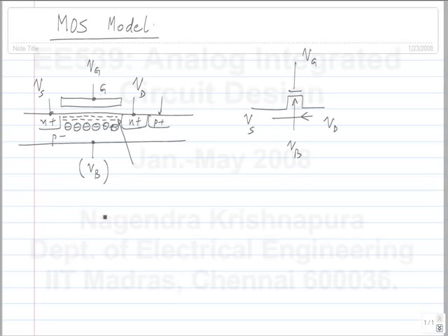So, you can think of this as, think of the MOS, that is how it was initially conceived. There is this channel, a sort of semiconducting channel, and there is a capacitance to the gate and a capacitance to the bulk. So as you increase the voltage of the gate, more charge is placed on the plates, and similarly as you increase the voltage of the bulk, more charge is placed on the inversion layer. Okay. So more charge will be available for conduction whether you increase the potential of the gate or increase the potential of the bulk terminal. Okay. That's why it's called the back gate. In a way, it's exactly similar to the gate.